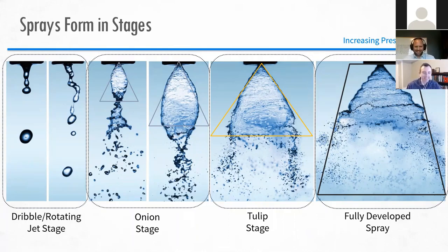I can answer that. I think it's one of the more interesting hydraulic sprays. With an air atomized spray, you can't see what the air is really doing. So having a hydraulic spray is a nice selection to visualize this process. And a hollow cone provides a thinned out center. So we've got this liquid sheet forming on the far right-hand side.